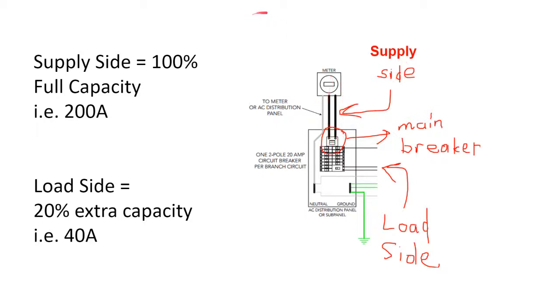Regardless of whether the power to the building comes from the solar array or the utility, the power is still throttled by that 200 amp main breaker at the top of the electric service panel. Alternately, a load side connection can be selected. The load side amperage allowance is less than the supply side amperage allowance, and so is generally selected for systems which will power less than 100% of a building's energy, whether it be a small battery or a small solar array.